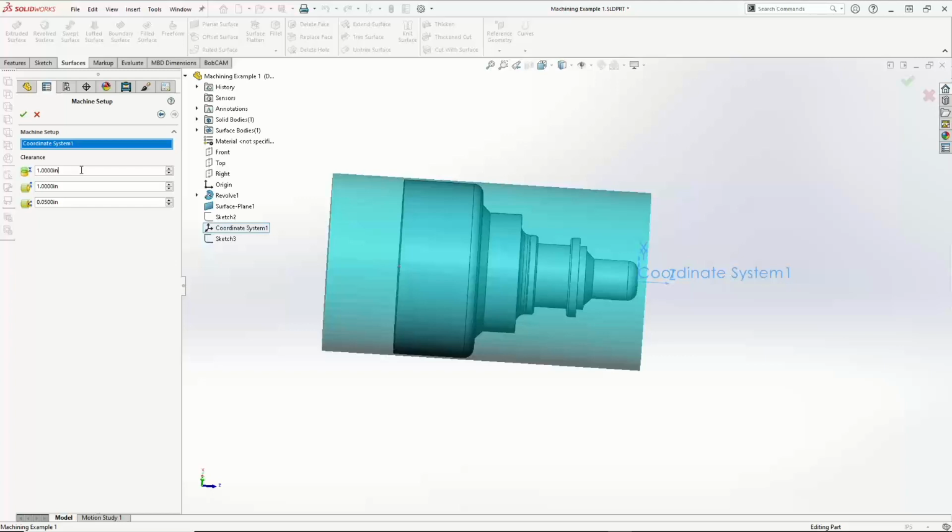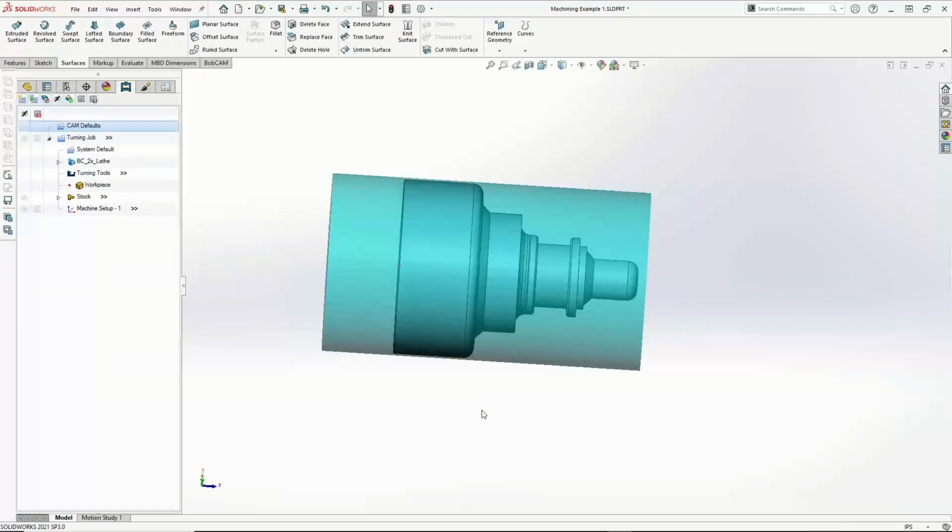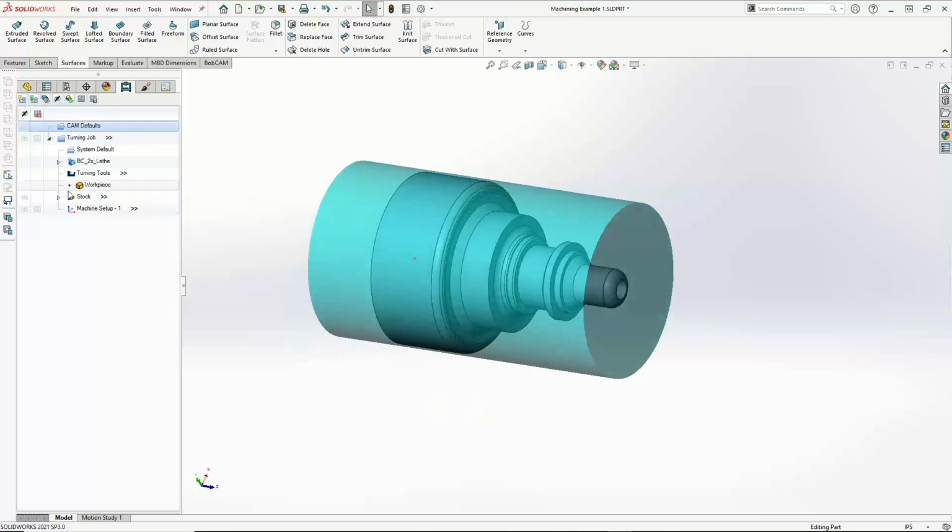And then for ID work, it's 50 thousandths. So it's going to pull that tool off the wall just 50 thousandths, and then it's going to feed out. So it hopefully is small enough to be safe. When we're done and we can't hit that next arrow anymore, we're going to hit OK. And that's going to lock that stock in.